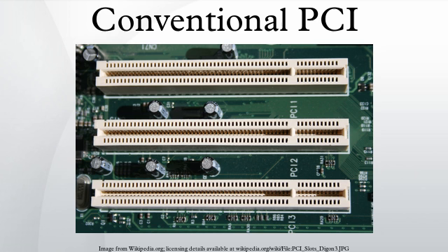0110, memory read, this performs a read cycle from memory space. Because the smallest memory space a PCI device is permitted to implement is 16 bytes, the two least significant bits of the address are not needed during the address phase. Equivalent information will arrive during the data phases in the form of byte select signals. They instead specify the order in which burst data must be returned. If a device does not support the requested order, it must provide the first word and then disconnect.